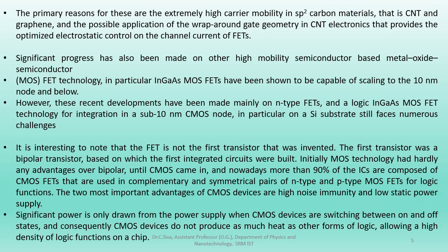Again, while other high mobility materials like indium gallium arsenide have shown potential, they face integration challenges in making CMOS logic on silicon substrate. Silicon dominated because CMOS offered high noise immunity and low static power. But CNT CMOS could provide further gains by reducing switching energy and heat generation.